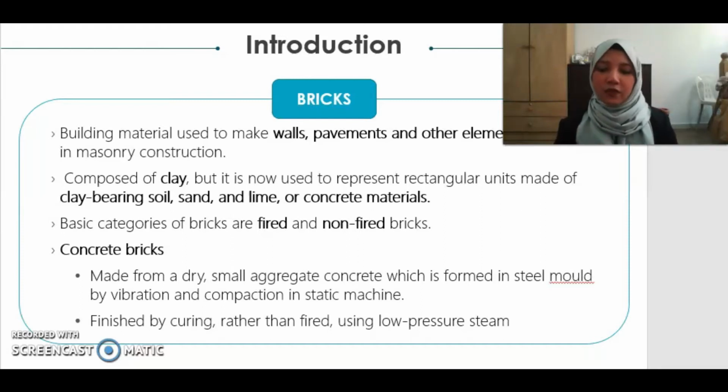But for our project, we focus more on concrete bricks, which are made from a dry, small aggregate concrete which is formed in a steel mold by vibration and compaction in a static machine. And it is finished by curing using low pressure steam rather than being fired.